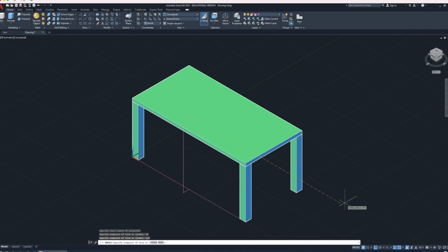that distance from the center of the body to the right shoulder should be 19.4. And then I'm going to go forward the distance from the shoulder to the fingertips, which should be 66.2. Type return to tell it I'm done. So now I've got a stick figure representing the torso, the shoulder, and the arm.